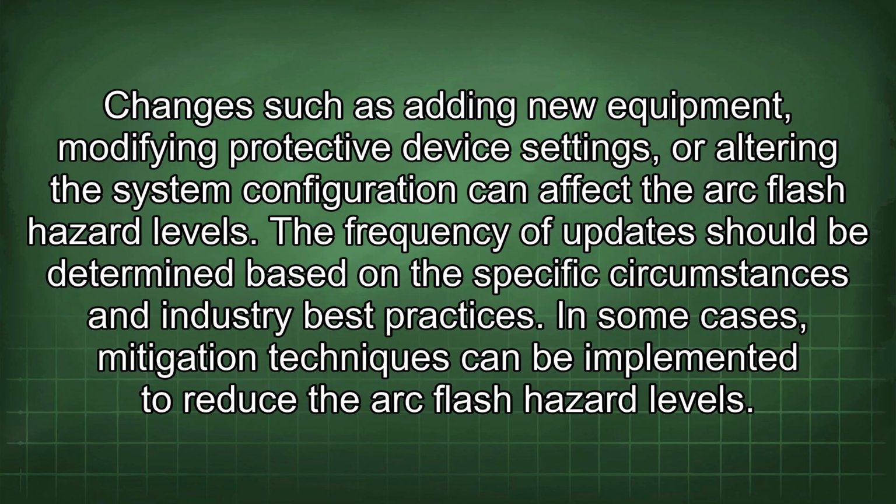It's important to update arc flash studies periodically, especially after any changes to the electrical system. Changes such as adding new equipment, modifying protective device settings, or altering the system configuration can affect the arc flash hazard levels. The frequency of updates should be determined based on the specific circumstances and industry best practices.